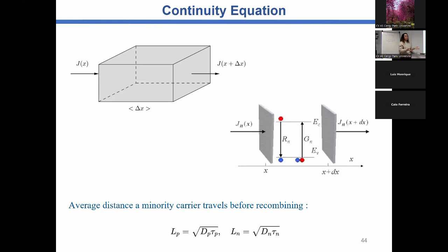Generally, we do it to see, but we must be careful, because if you put two points like this and like this, it is different. If you increase the distance, you must have a higher resistance. So if you want a quick comparison to know if your material is more conductive than another material or another treatment, you can just use your multimeter and measure it.